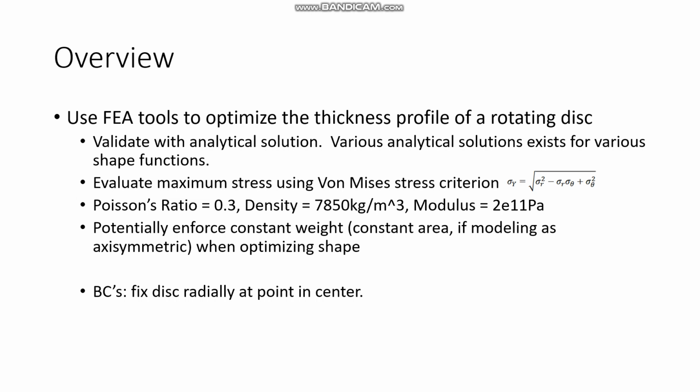And then for a boundary condition, as we've done in previous homeworks, I will be fixing the disk radially at a point in the center just so that we don't have any rigid body motion. If using Abaqus, I may be able to just apply some inertial relief.